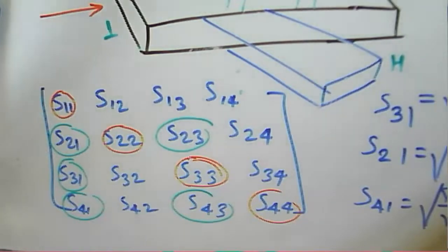We are supposed to consider ideal components in a laboratory. In a laboratory, most of the sources used have a reflex klystron, or we consider the Gunn diode. Mostly in all the measurement setups, people use a reflex klystron because it has a 1 kilohertz modulated source, and through that we are able to obtain the guide wavelength, the impedance and everything. So the reflex klystron will provide the 1 kilohertz modulated output.